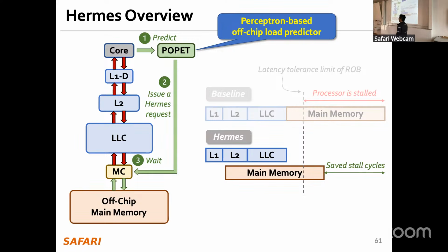Yes. So in this case, the L1 cache is virtually cached, and from L2 it is physical. That's correct. And what if the design of the architecture is different? Probably you can also do it differently. Let's say virtual caching up to a lower-level cache: until L2, make it virtually cached, and only from the LLC physically cached. Then should this also change? If I'm not mistaken, your question is, if my L2 is virtually addressed, does this need to change? Exactly. No. What your short-circuit path is trying to access is the main memory. Your main memory is still accessed by the physical address, right? So you can still cut across this entire hierarchy, even if your L2 is made virtually addressed.